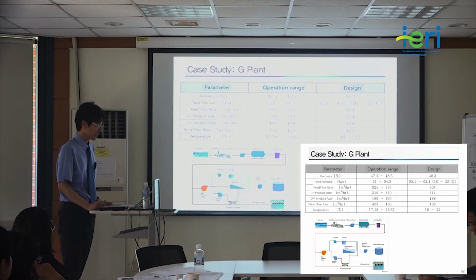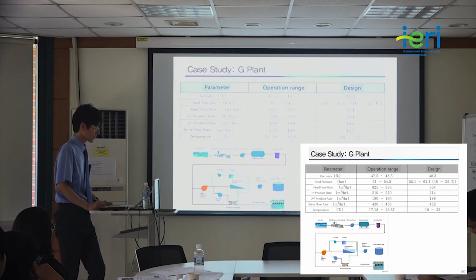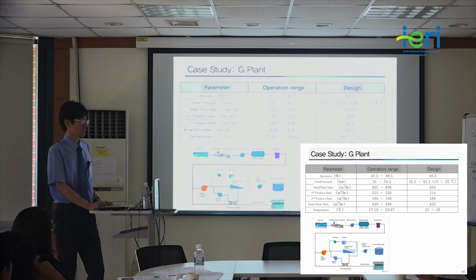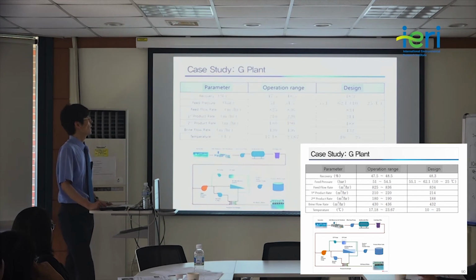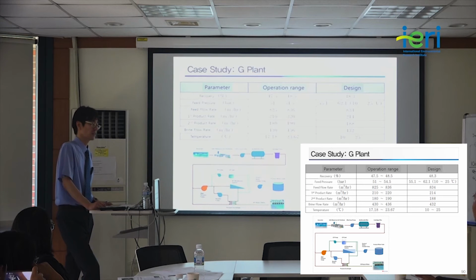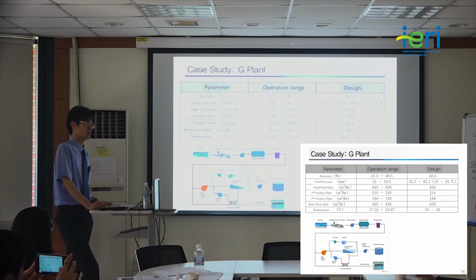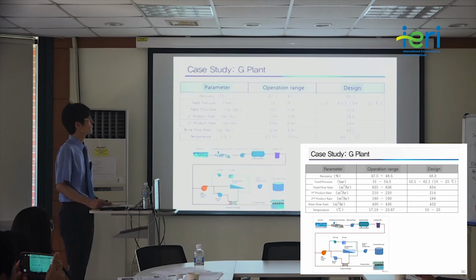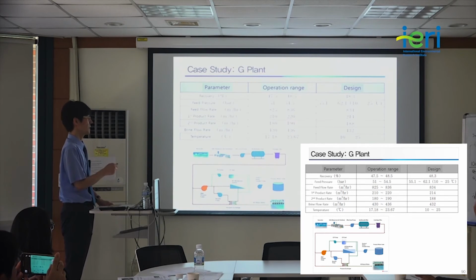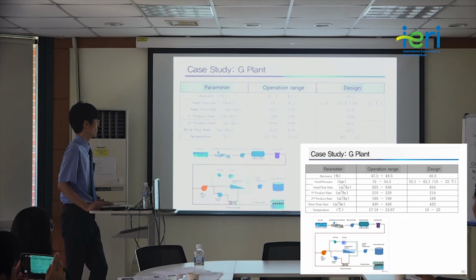So this has a recovery of around 48%, and the feed pressure ranges from 51 to 54.5. Again, since Korean seawater has a salt concentration of around 30 to 32 thousand milligram per liter, considering this salinity, we can operate this system with moderate pressure conditions.